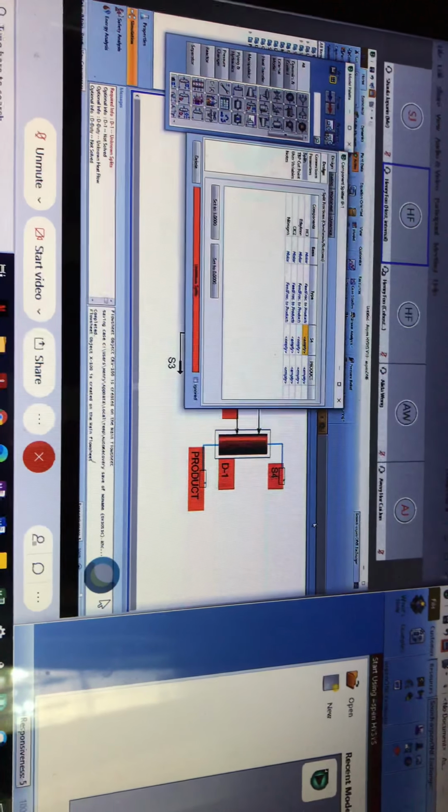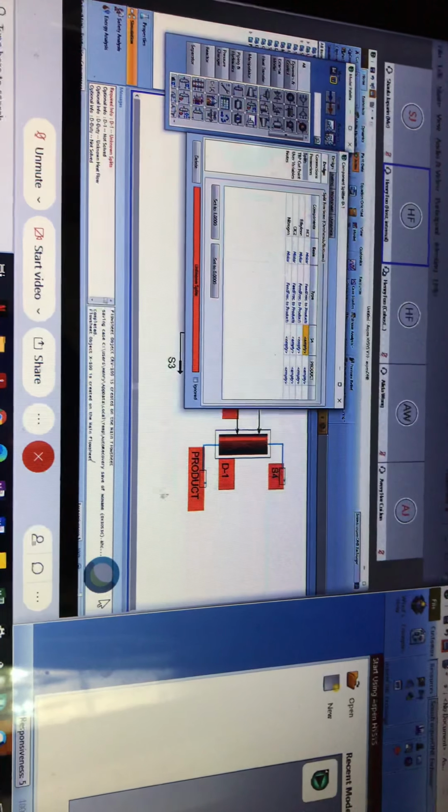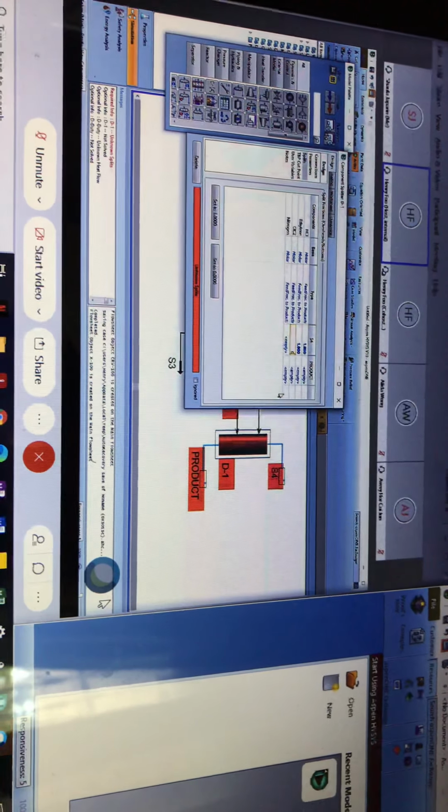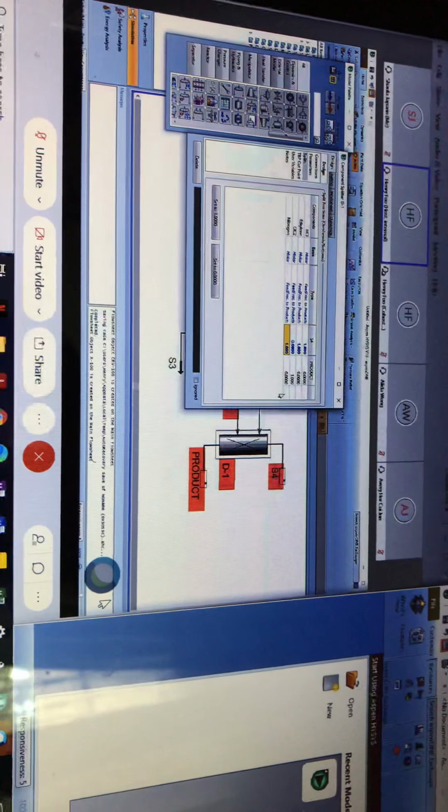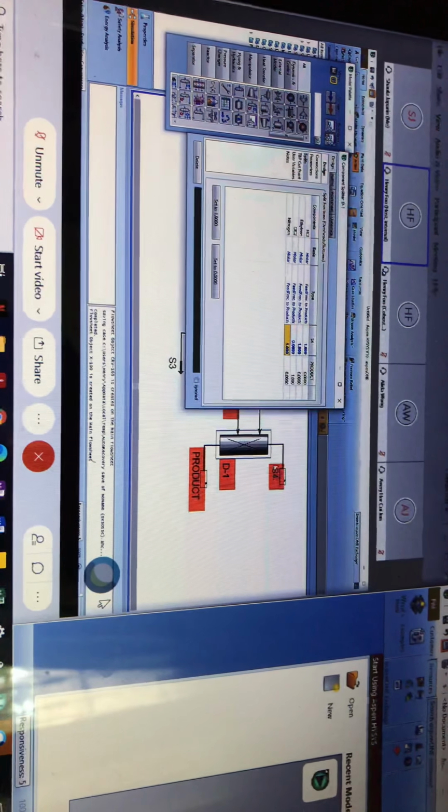Basically, you just follow exactly the same words being asked in the question set. And then next step, split. Here we have to define the ratio. How many percent will you split into the stream of S4 or split into the stream of product? So in this case, we have to define for S4 as 1, 0, 1. It means we're defining the stream S4 should only contain species of HCl, ethylene, and nitrogen.